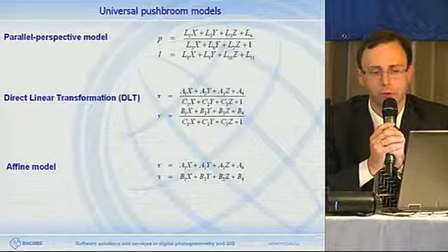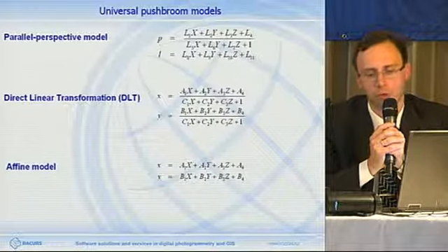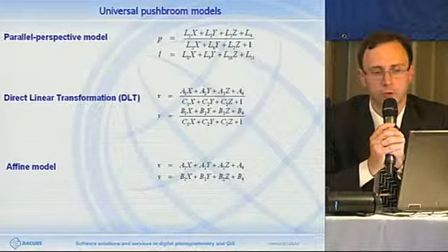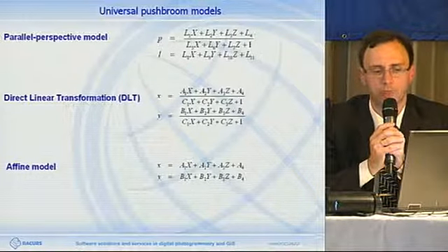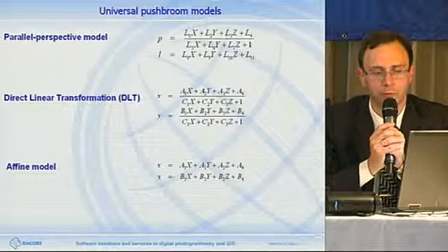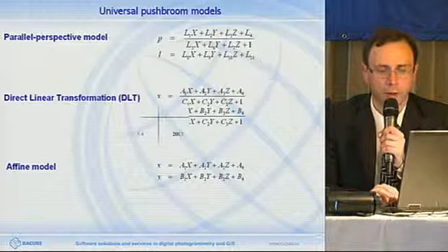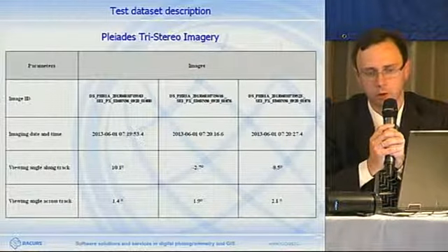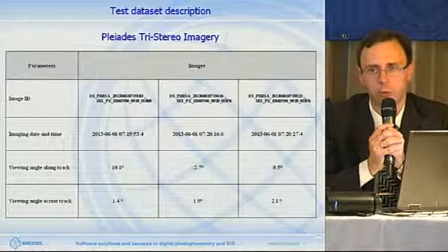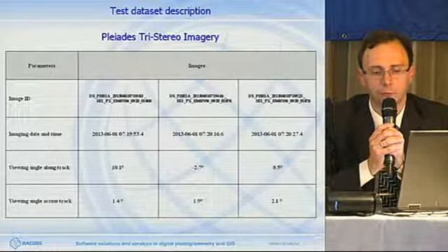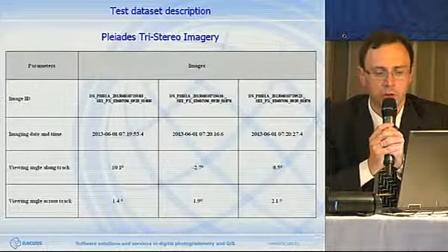For instance, sometimes the system of coordinates where these GCPs exist is unknown, and we need to use the same system of coordinates for the output product, and to establish parameters is hard sometimes for one particular purpose. And in that case, it is impossible to use metadata, for example if RPC is attached to WGS 84 and we need another system, and then we'll have to use a universal model, although it's still better to avoid it.